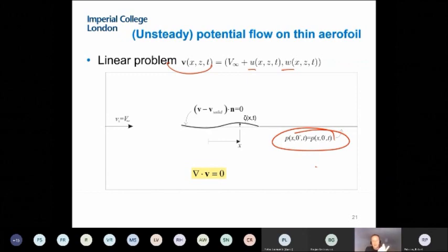It has thickness, and everyone that has seen a CFD plot sees that actually you have a trailing edge driven wake, which is substantial. It's typically the thickness of the airfoil once you go a few chords downstream. Now, because we are making all these potential flow assumptions, we can get away with this model. And again, it's an excellent model for what we care about, which is the lift-driven problem. So it will be terrible for drag, but that's not what we're after.